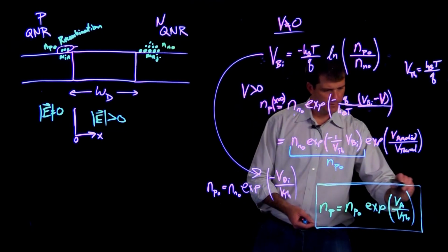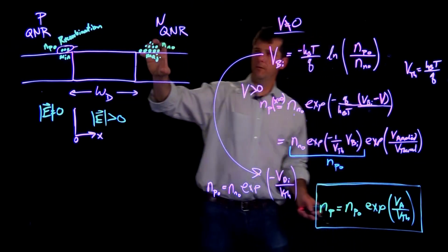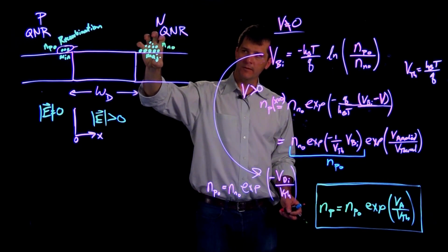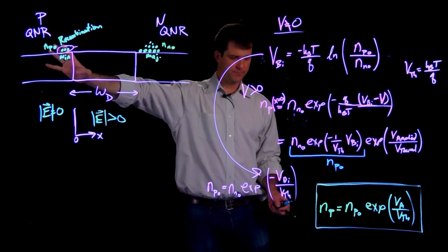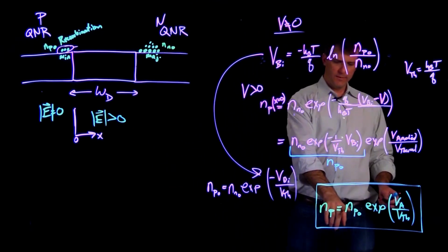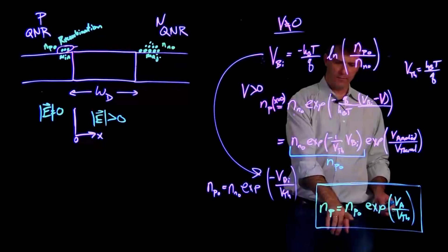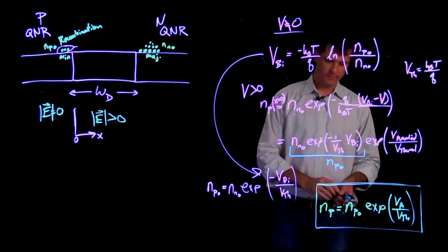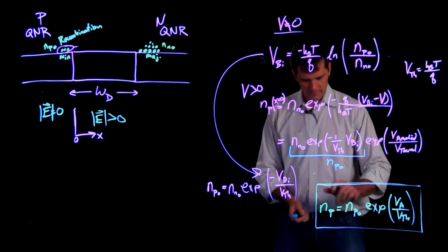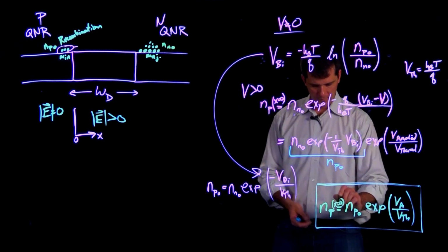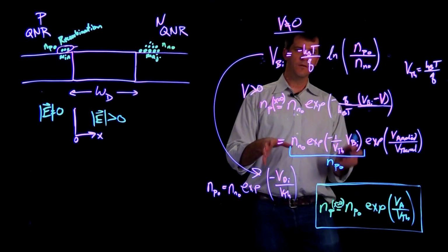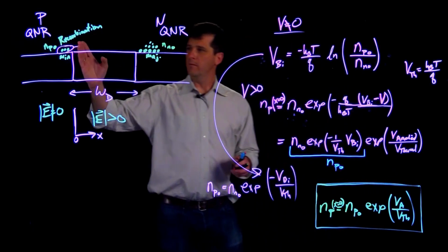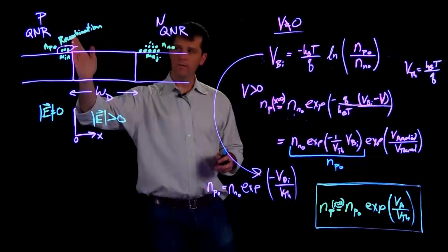So it's really interesting that we started out with considering the concentration on this side of the junction, the electrons as the majority carriers. We inject them across the junction, and what ends up happening is that we reduce it to an expression where the minority concentration on this side is actually controlling the current. So we've gone through and derived our boundary condition, which is voltage dependent, for the minority carrier concentration on the p-type side of the junction.